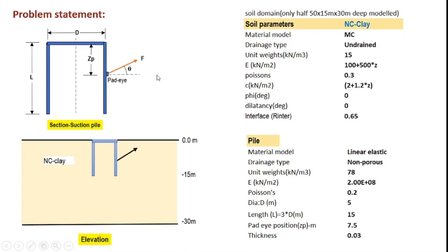Please remember that the pad is the location where the mooring tension will be transferred to the suction anchor, and the location of the pad requires multiple analyses so that we ensure that the maximum capacity of the anchor is mobilized with translation as the main mode of its deformation behavior with a minimum rotation.